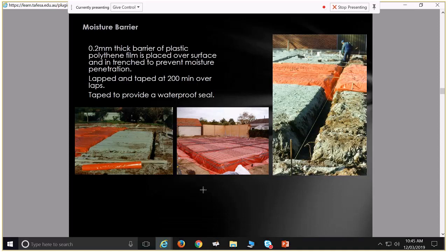So you've possibly done termite spray and installed your pipes and done all your beams. Next thing to do is install all the plastic, so that vapor-proof membrane. This stuff here, I'll pass that around if you want to see that.